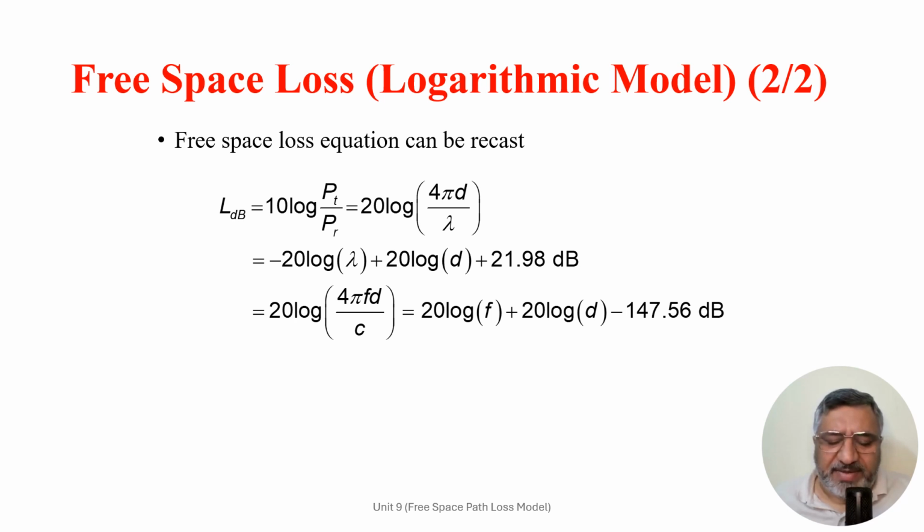And finally, we can convert our equation in terms of frequency. So we can write loss is equal to 20 log f plus 20 log d minus 147.56 decibels.